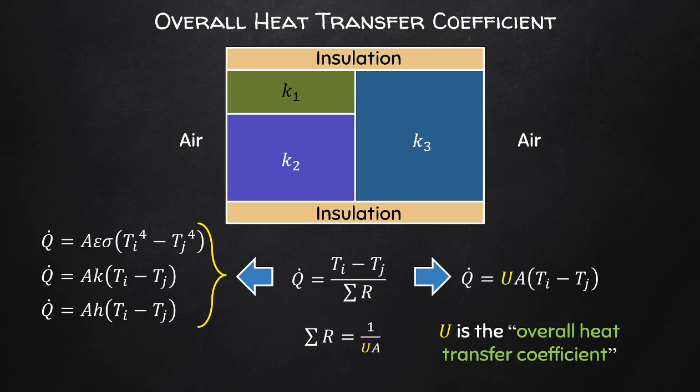Often we can approximate fouling resistance. So this is where the pipes tend to create layers over some period of use. Maybe it is calcium scaling, etc. And these can also be determined and factored in when you design a heat exchanger.